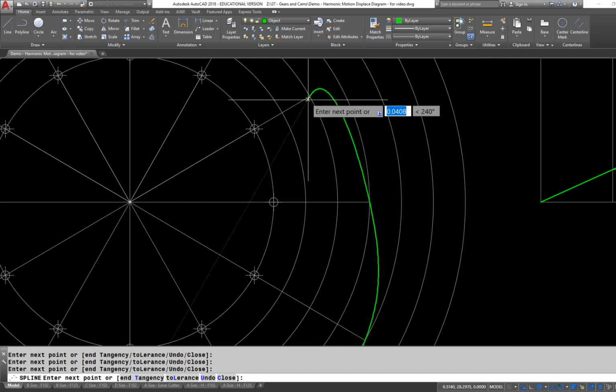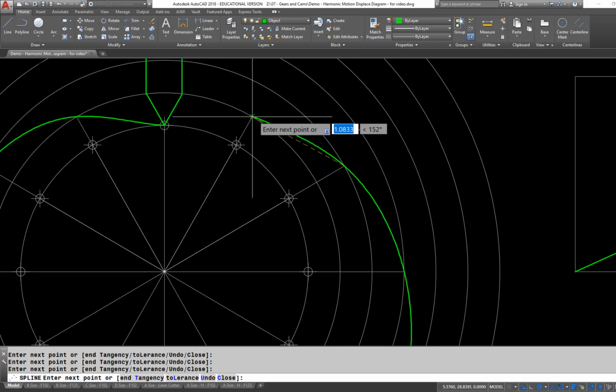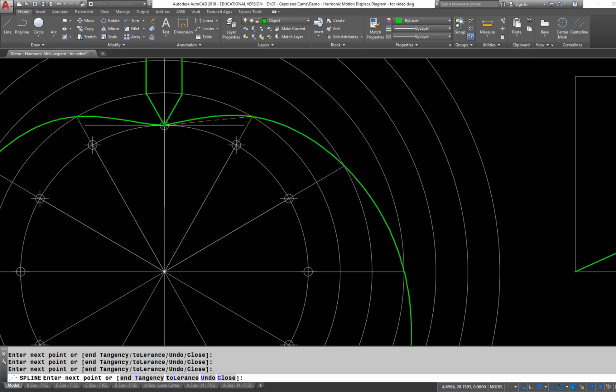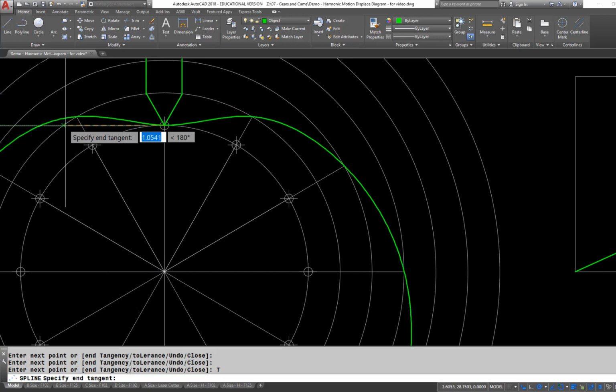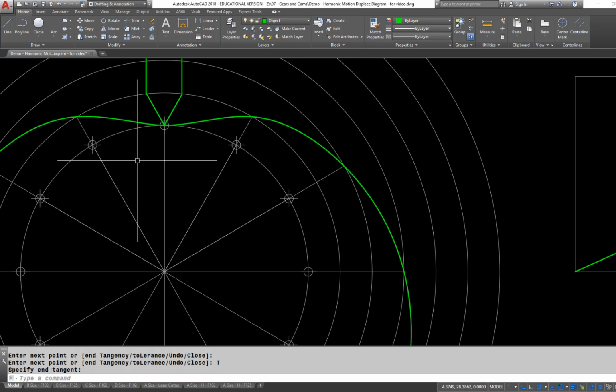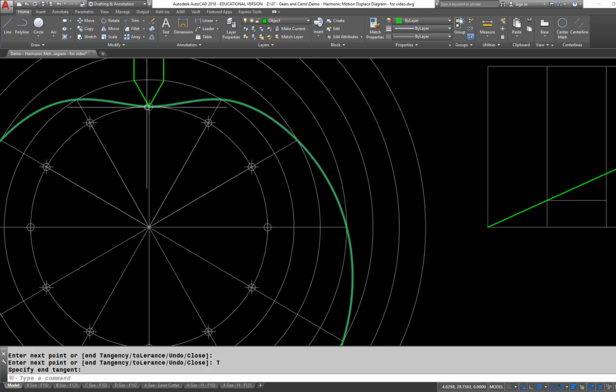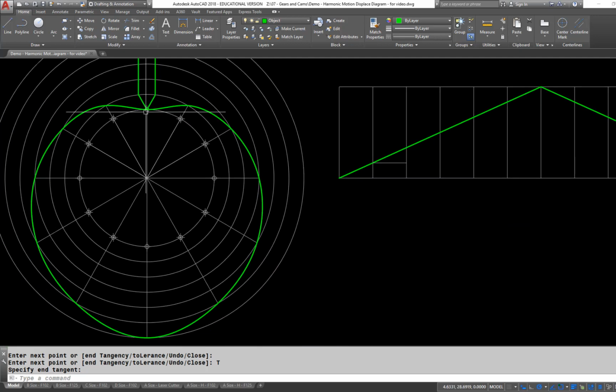We're getting there. That's an intersection, and that's there. And now I'm going to go back to here, and then I'm going to smooth that out also by adjusting the end tangency and going nice and smooth here. And we'll zoom out, and that's what our cam looks like. You can see that we're going in a uniform accelerated motion till we get all the way out here. We did smooth it out ever so slightly so that it's not just forming a peak right here. We just smooth that out using tangency.